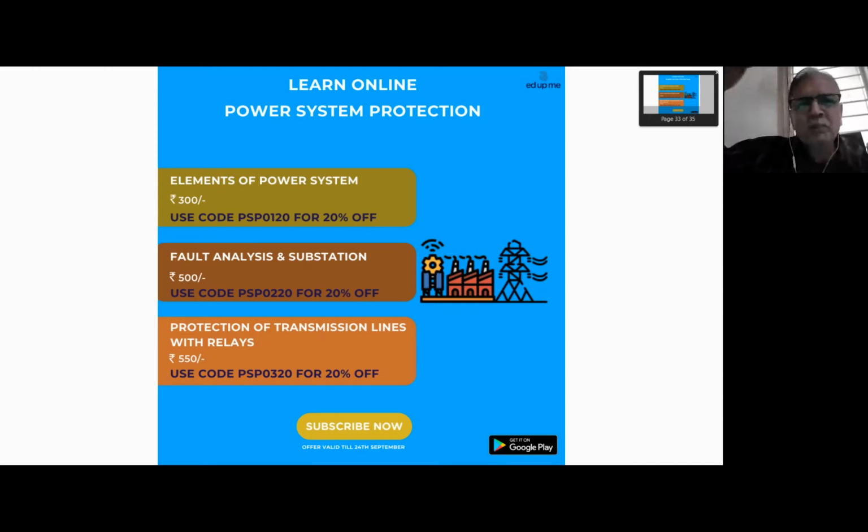So one must have some switching sense available, and that will always be available from the system, because when something is switched off or switched on, only then would you like to change the settings. So it can be changed from the manual, from the closure of the circuit breaker switch using binary inputs. As many as 16 binary inputs and 16 binary outputs are available in modern numerical relays. Please, I think I am trying to satisfy your question.